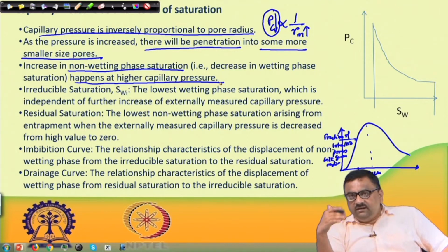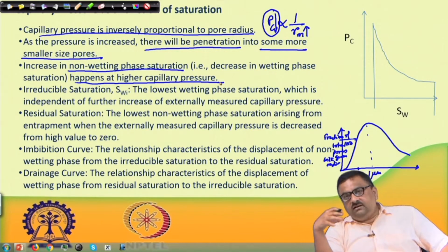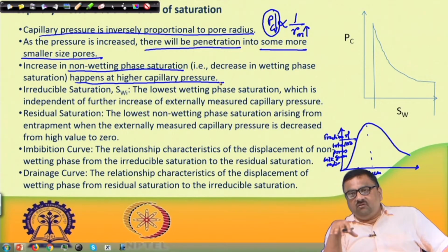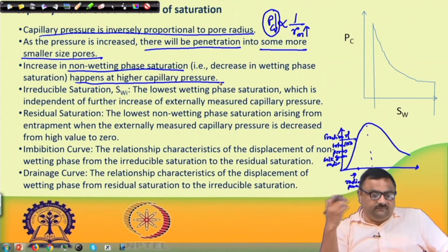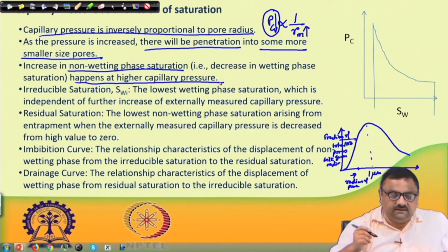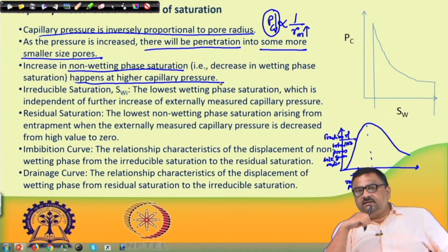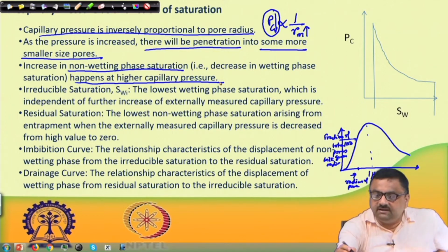But now, if we increase the pressure of the oil, I expect some of the water will be moving out of the core, and in that place some of the oil will be getting in, and that differential pressure we are referring to as capillary pressure. Now, if somebody plots this capillary pressure with saturation, it would appear something like this.